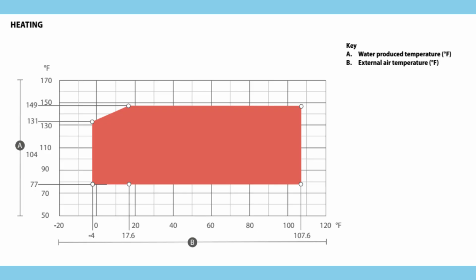Now, coming to the main question, how should we switch the mode from the cooling loop to the hot water loop during winter for the terminal load loop? In multifamily or commercial systems, you don't flip between heating and cooling in a moment. There's always a buffer period to stabilize water loop temperatures and protect compressors. Heat pumps have a safe operating envelope.